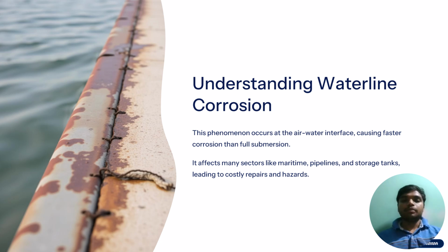Chemical reaction: the interaction between the pipe material and water can lead to corrosion, especially in the presence of aggressive water conditions. For instance, water with low pH can accelerate the corrosion of metals like copper and steel. Additionally, the presence of dissolved salts and other chemicals can exacerbate the problem.